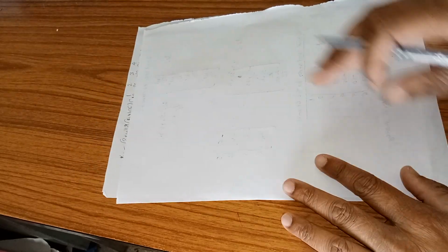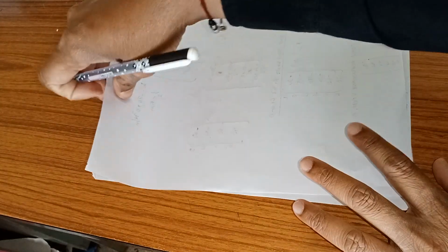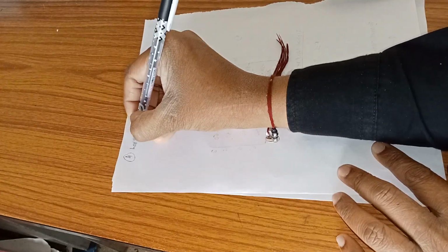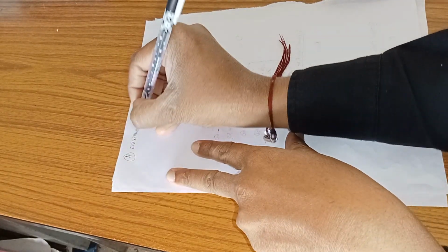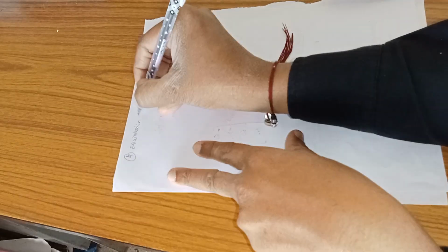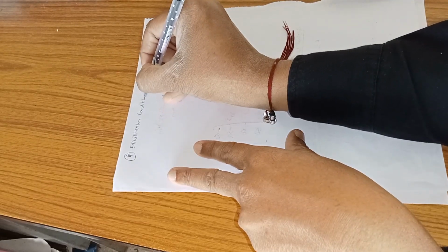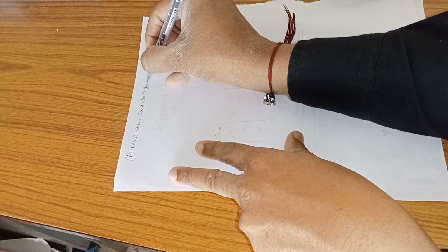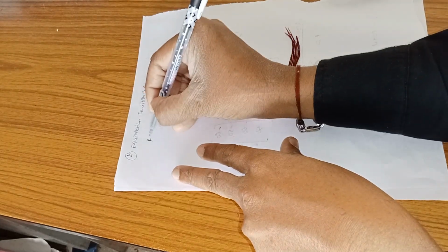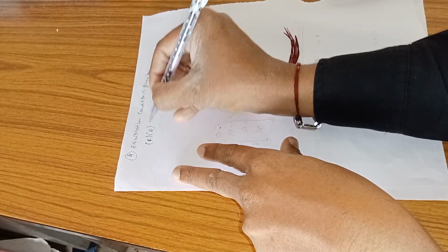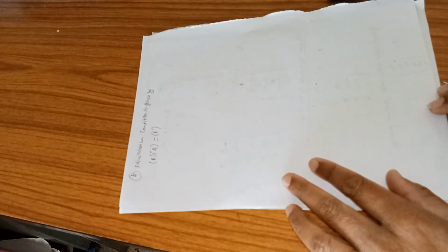So the next step will obviously be the equilibrium condition. Let me write the equilibrium condition. That is going to be step number 4. Step number 4 is the equilibrium condition, which is given by K into Q equal to F. So K is the global stiffness matrix, Q is the global nodal displacement vector or displacement matrix, and F is the global load matrix or global load vector.